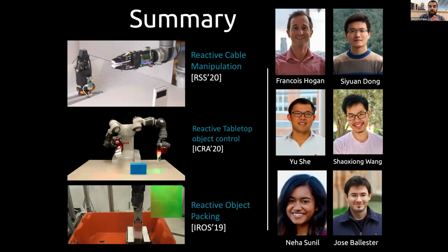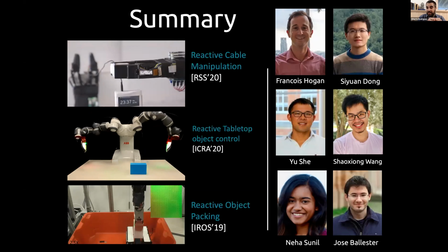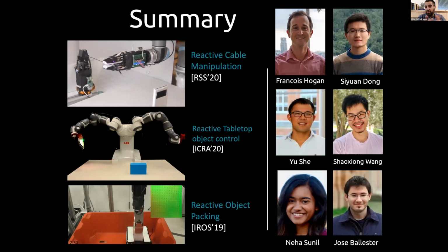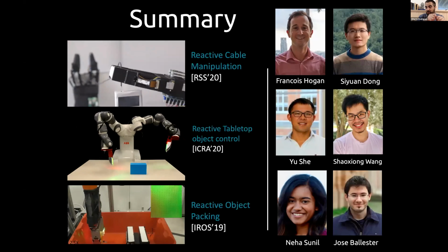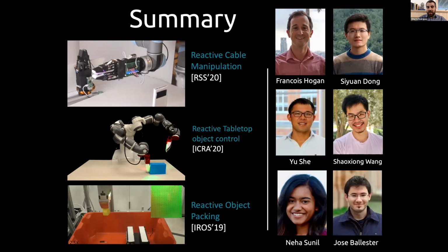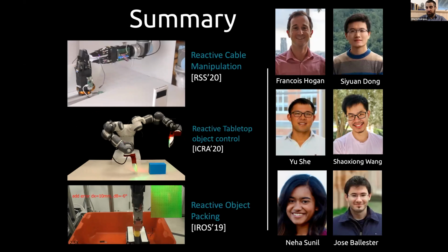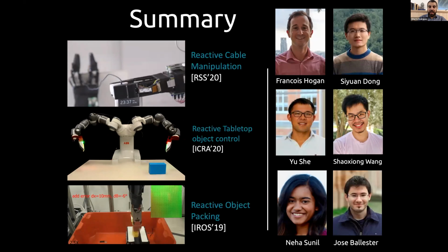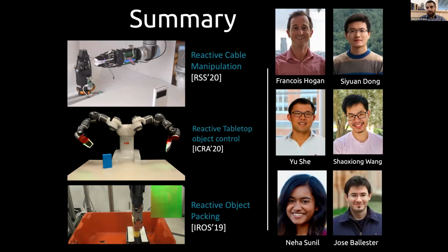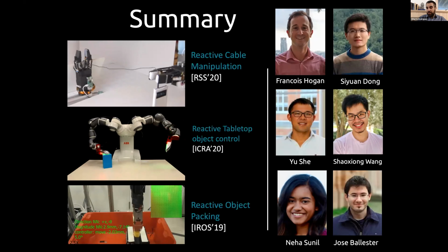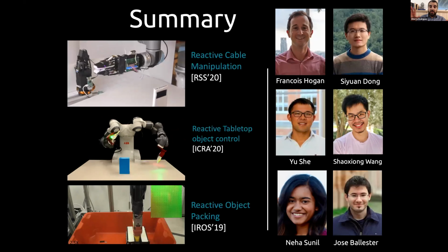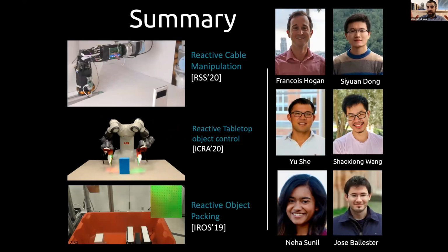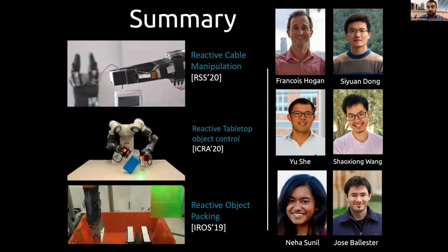So we know where the cable is when it's in between the fingers. We just use standard image processing algorithms to make the best fit of the contact patch between the fingers and the cable, and then we fit an ellipse to that to get the axis of the cable. But wherever the cable is outside the fingers, we don't care, to first order.